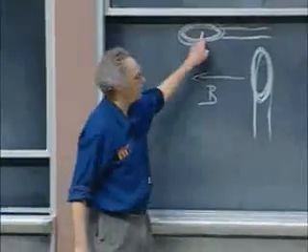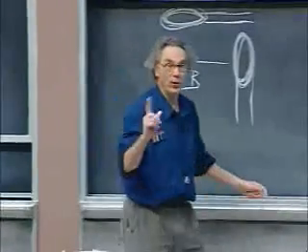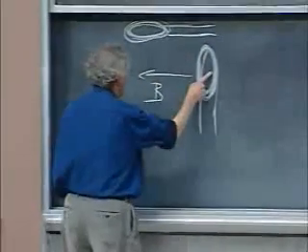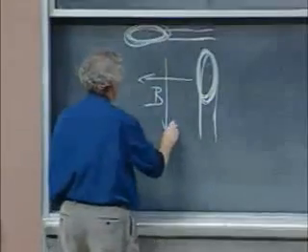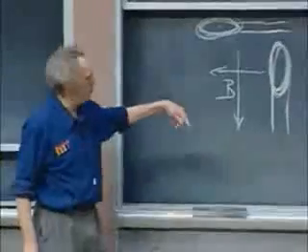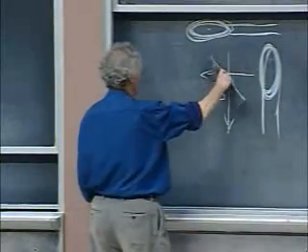Then there is no current here. But 1/4 of a period later, this one has no current, but this one does. Let's assume that now the magnetic field from this one is in this direction. And so what you're going to see now is that again you have a rotating magnetic field which goes like so.